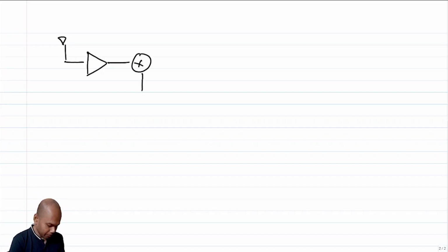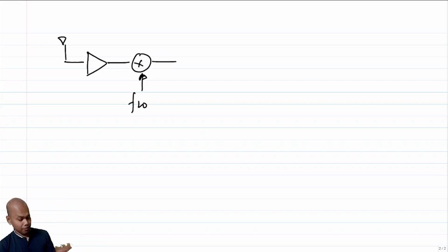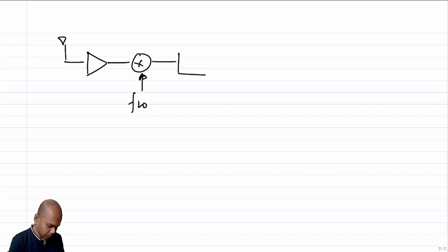So now let's switch our focus to the transmitter side of the transceiver. If I have to draw the entire thing right now, what did we have? We had a filter, we had an antenna, then we had the image reject SAW filter and LNA with a transmission line. Then we had a mixer. This input was at FLO. Now, depending upon whether you have a zero IF receiver or a heterodyne receiver, you might want to have a low pass filter or a band pass filter.